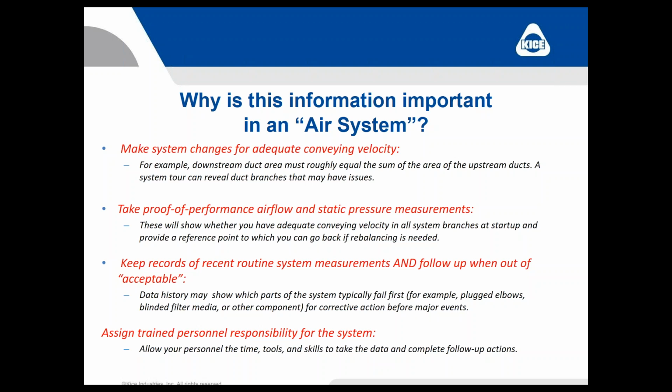The last one, almost to the end here, why is this information important? Well, again, you want to make sure your system has adequate velocity so that the dust goes all the way through the line. So you have to keep it relatively equal even as you add branches. Proof of performance, airflow and static measurements.